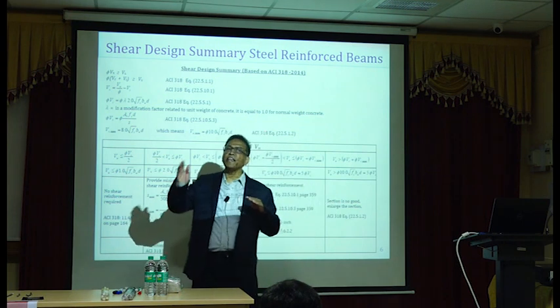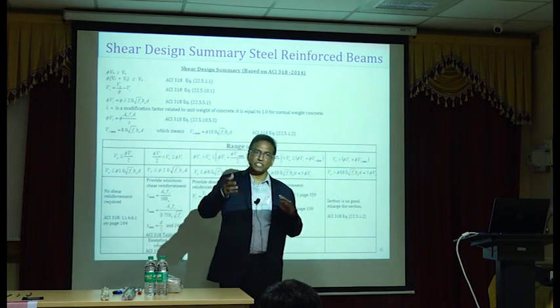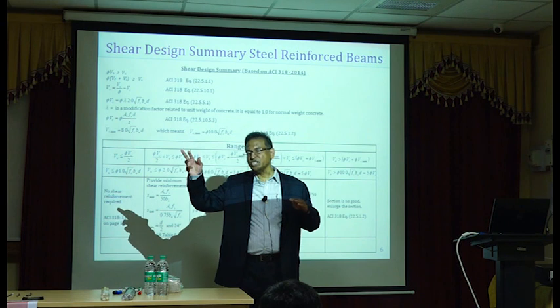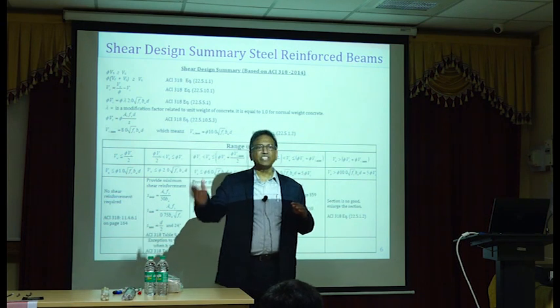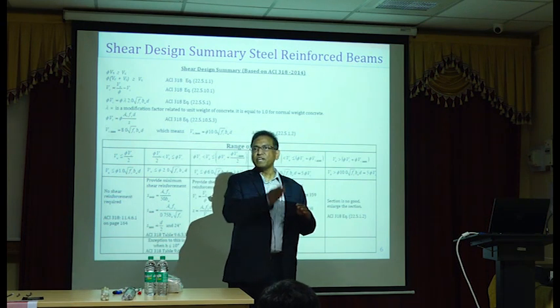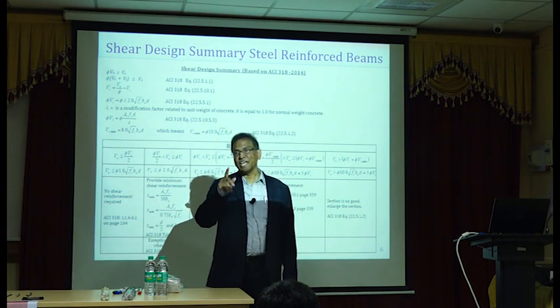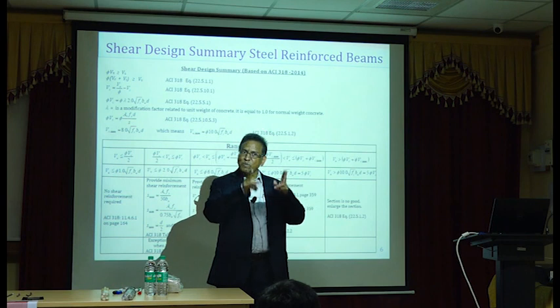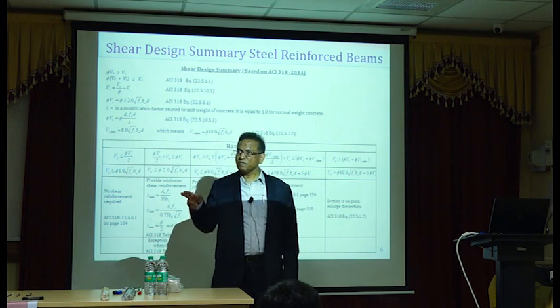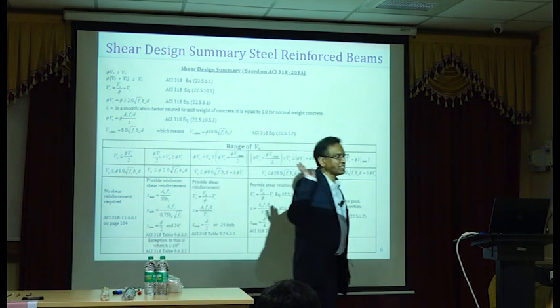The steel bars can even go into the strain hardening range, as long as you prevent shear failure. If you prevent shear failure, it will have lots of reserve capacity, and that's the reason in earthquake resistant design you have special provisions for shear reinforcement detail, right? You remember that? That's the reason.